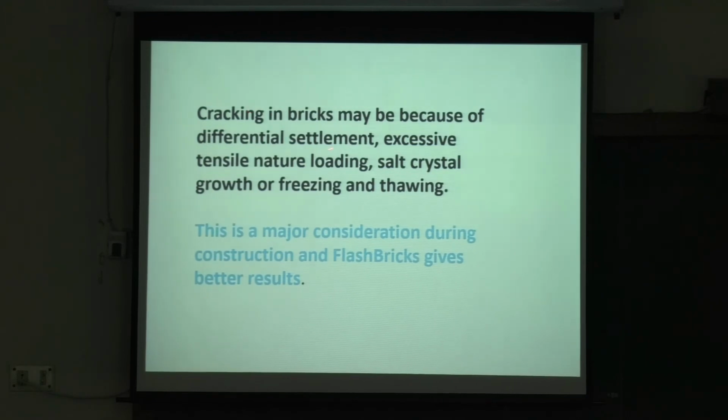Cracking in bricks may be because of differential settlement, excessive tensile flexural loading, salt crystal growth or freezing or thawing. This is a major consideration in construction, and fly ash brick gives better results.